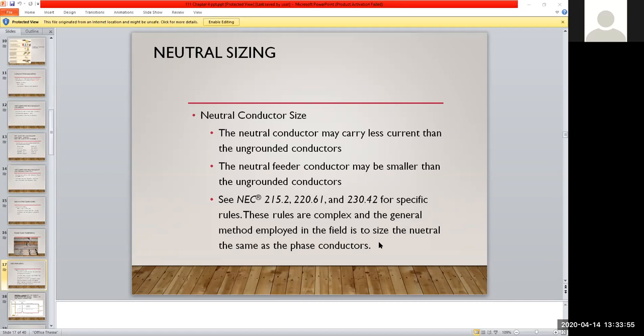But yeah, the neutral is more often than not going to carry the heavy current loads, because usually the hot will deliver through the receptacles and the lighting and whatnot, and the current's being used by a device, right? But you have to have a current traveling path to go back, right? But more often than not, you're not going to have too much current going back on the neutral. And if you have no devices at all hooked up and everything's wired correctly, your neutral really shouldn't have anything on it. But you always got to take that with a grain of salt, that the electrician before you knew what he was doing. You get people out there wiring stuff that shouldn't be.